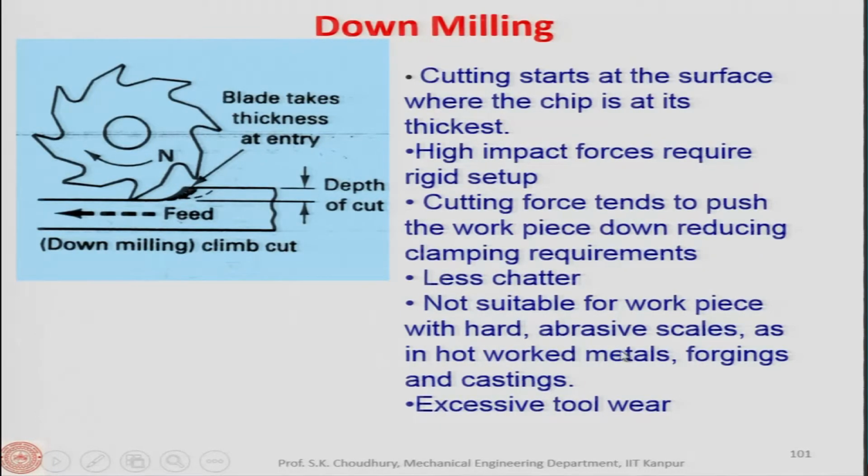Then of course the tool wear will be more and even the tool may break. In that case the tool wear will be excessive, and that is why it is not suggested that down milling is performed immediately after casting or after the metal working process, because the layer at the top will normally be harder than the layer lying inside, or the hardness of the top layer will be more.